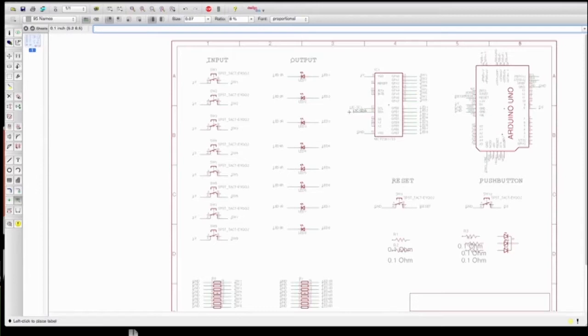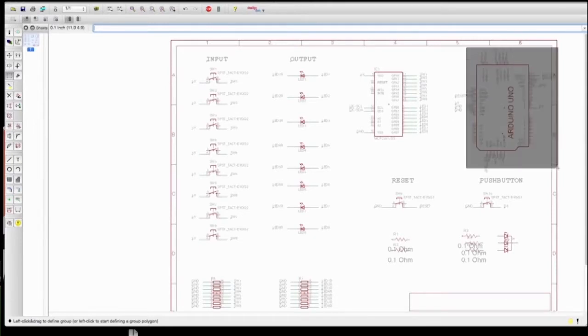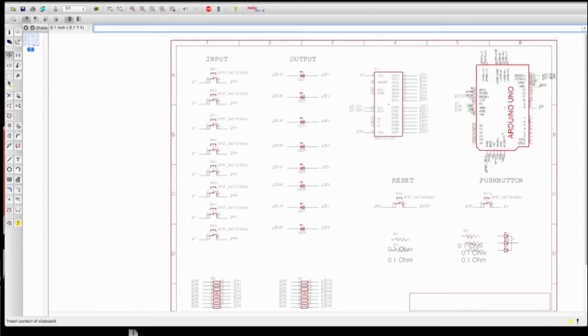We still have to do one more thing with the I2C bus because we want to bias the voltage high, although it probably wouldn't matter as much on the current board because it's not really going anywhere. All right, you see, this is going to drive me nuts. This would work perfectly fine, but I have to rearrange the Arduino because these labels are off the thing.